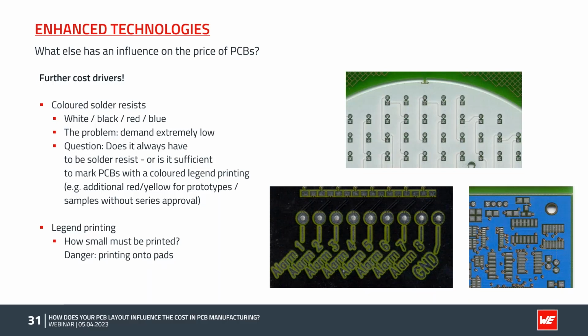So this is a point for us, what we always need to check during input and design rule check. Is there legend printing going on top of the solder pad? Then we have to remove it during our CAM phase. And again, it's a quality thing.